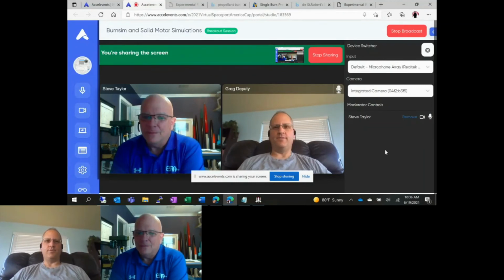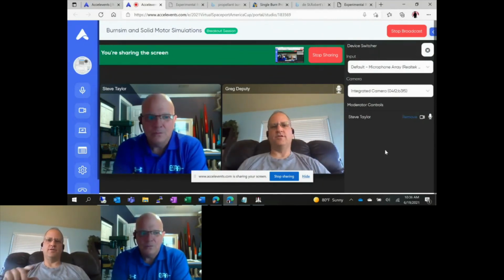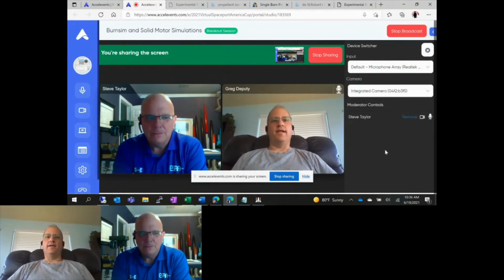You need to have a way to, number one, measure that. So my approach is doing test motors moving from short motors into long motors, so your mass flux is changing, and look at your test data and identify, okay, mass flux gets to here, I'm seeing the burn rate accelerate this much. Mass flux is higher, the burn rate's accelerating more, and quantify that in some way.